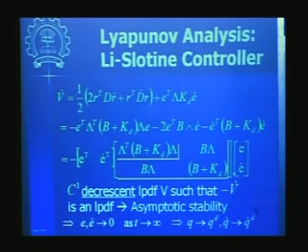So we have the asymptotic stability result by way of the Lyapunov theorem on asymptotic stability. This is how we reach this asymptotic stability result. Now what this asymptotic stability means is that E and E dot are going to go to 0. This is the error which is going to go to 0. Now if you recall the definition of E, it's nothing but Q minus QD.